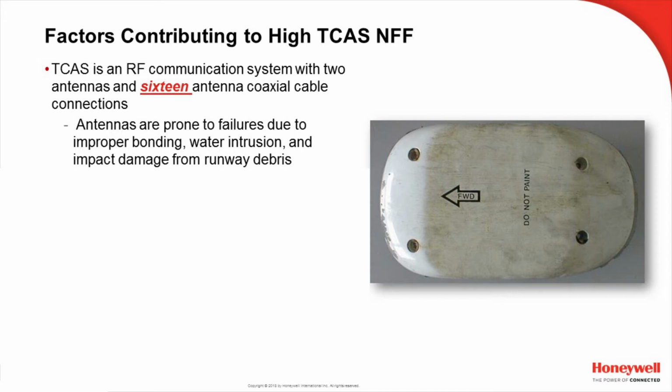especially the bottom antenna, because oftentimes humidity will condensate and will settle in the bottom of the fuselage. And if you are troubleshooting a bottom antenna problem, you'll go out, you'll find an excessive amount of corrosion because the antennas have been in standing water for a long duration. Also, the bottom antenna is subject to impact damage from the nose wheel tire throwing up runway debris. And as the fiberglass shell is nicked and scratched, little cracks form. Again, that's another way for water to intrude and to disrupt the elements in the transmission pattern.